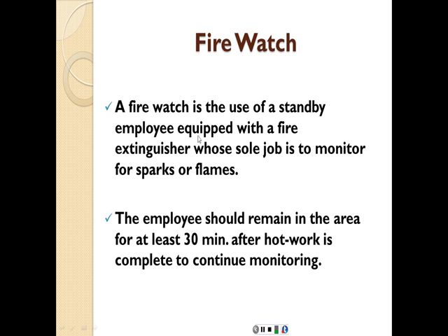Basically, a fire watch is the use of a standby employee equipped with a fire extinguisher whose sole job is to monitor for sparks or flames. So they're not doing anything other than watching for the flame spread or for sparks. This employee should remain in the area for at least 30 minutes after hot work is complete to continue monitoring, especially, as I said, in case of welding.